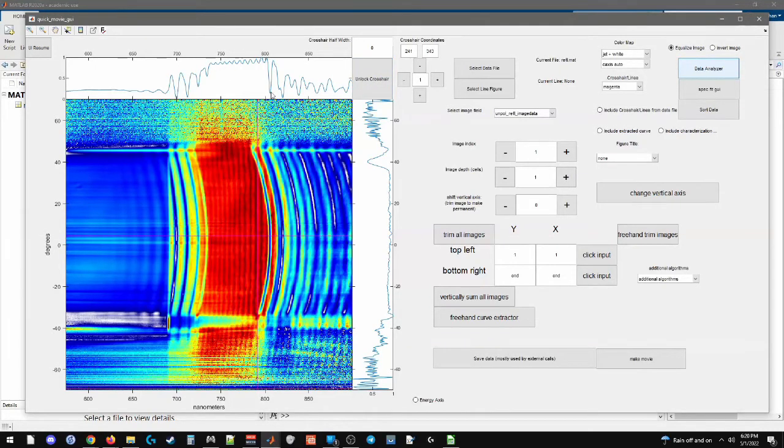Stop band in the middle, Bragg modes out on the edges, heavy absorption due to gallium arsenide, aluminum gallium arsenide, 20% alloy, so that puts the band gap or the absorption edge at like 680, 690 nanometers, and so you see everything below that is basically just absorbed. And so we're going to try to fit our simulation to some of this data.